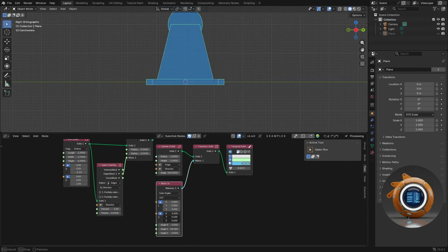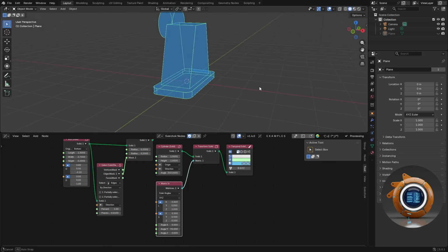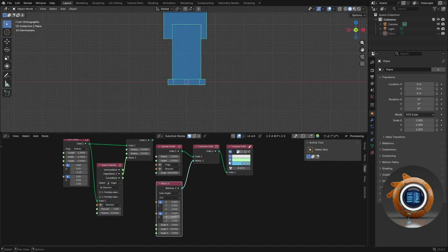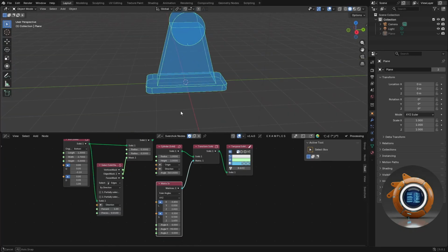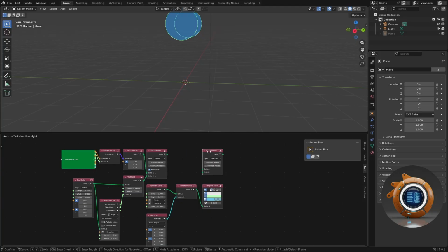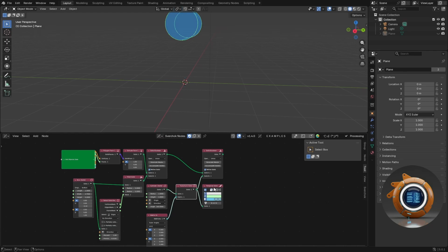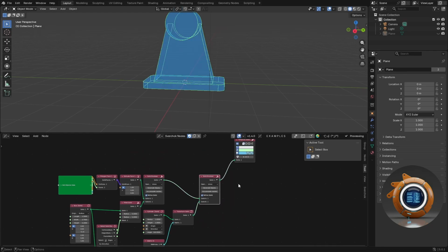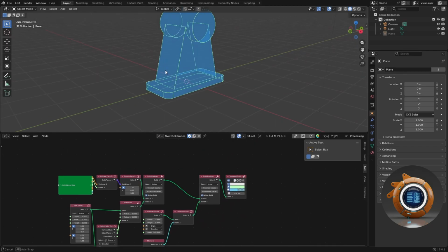Scale it on the x and y axis to make it smaller and on the z axis to make it longer. Add another solid Boolean node in union mode to join this part to the top of the object. Whenever you see me creating a temporary viewer, it is not magic. Just Control and left-click on a node.